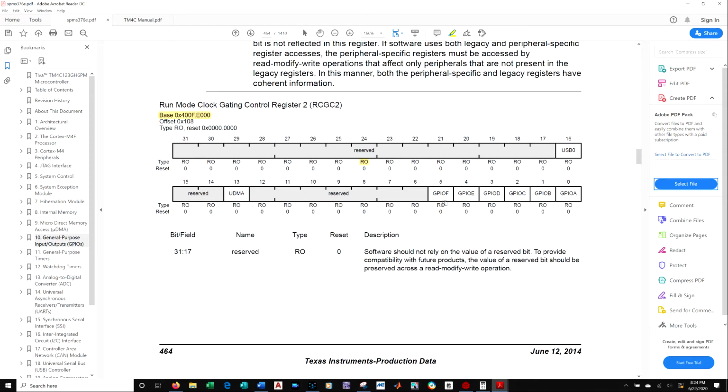All right. The next thing we want to do is set direction, and that's like telling the pin, is it an input or output? And step 3 is going to set the pin as a digital pin, so high or low, and that's it. So let's start looking at our code here, see what we got.